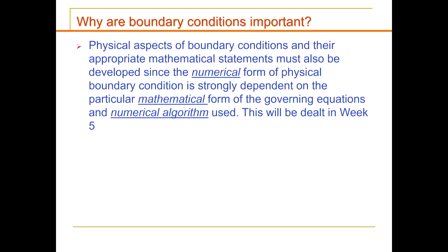So what I'd also like to cover in this course is to look at the boundary condition from a physical point of view. You may need to modify your geometry to set the boundary condition. Mathematically, a boundary condition has a certain format or feature, which you cannot always use to mimic the real physical boundary condition. But you can modify your geometry to mimic the real physics. This is something I will talk about when I talk about boundary conditions in week 5.